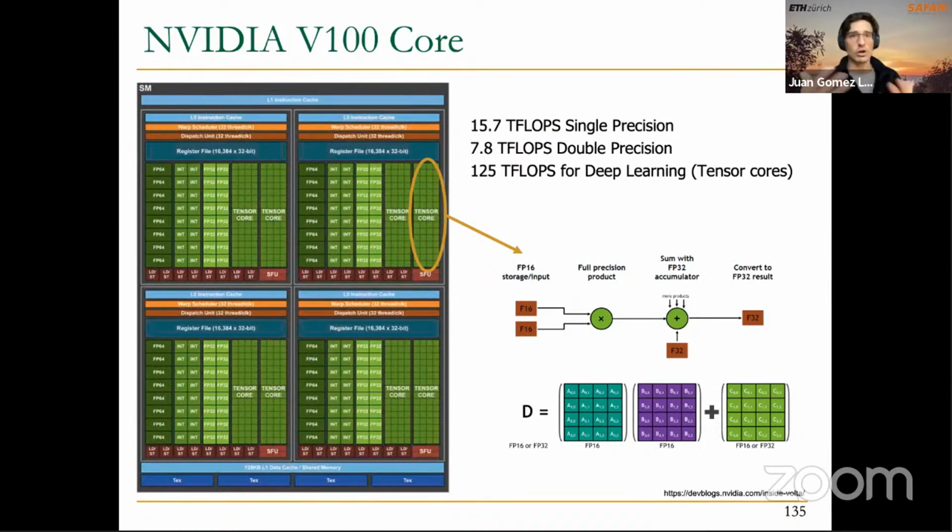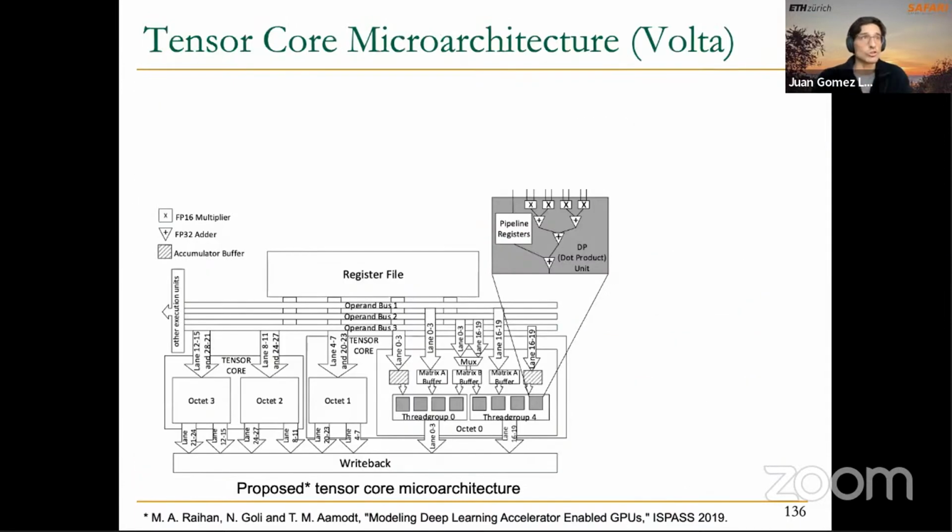But you can see here the combination of vector and array processors, and you can also see here many more concepts that we have covered in the lecture. For example, you have a memory space here that is called the shared memory. This is a banked memory as well. And actually this is interleaved in a kind of naive manner, so it's very frequent to have bank conflicts in the access to this shared memory. That's also something that you can watch in our GPU programming lectures, where we talk about how to deal with these bank conflicts and try to minimize them from the software point of view.